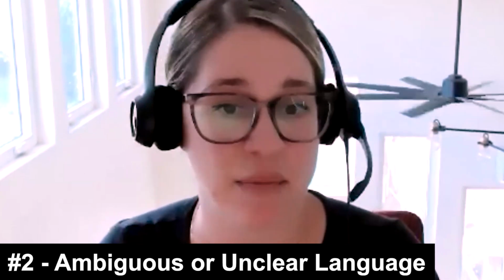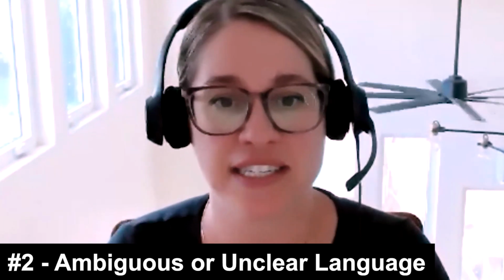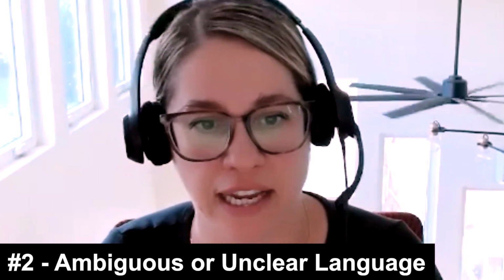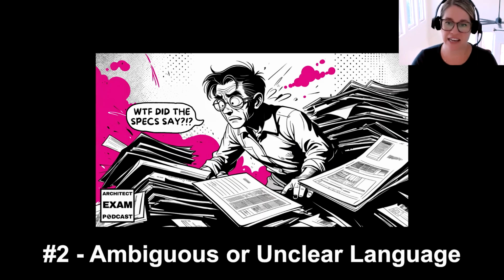All right, so next up we have mistake number 2, which is ambiguous or unclear language. So ambiguous language, what do I mean by that? Well, this is honestly the most stealthy mistake because it's so easy to make without realizing it. You've probably heard ambiguous phrases before, something like high quality finish or industry standard installation, or my personal favorite, as required. These are vague terms and they force the contractor to make assumptions that rarely align with what we actually intended for the design.